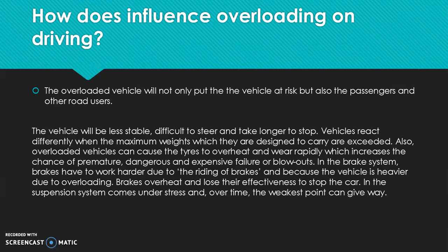Then how does overloading influence driving? Overloading on driving is dangerous for these reasons. The overloaded vehicle will not only put the vehicle at risk but also the passengers and other road users. The vehicle will be less stable, difficult to steer and take longer to stop. Vehicles react differently when the maximum weights which they are designed to carry are exceeded.